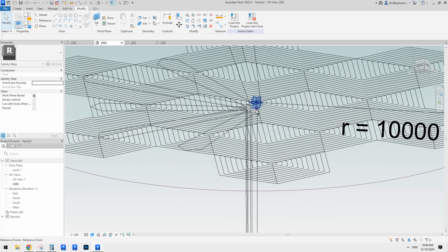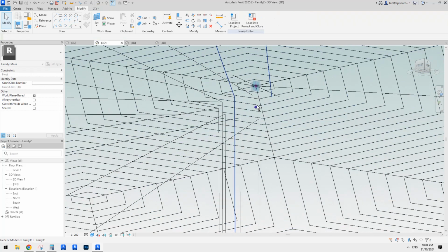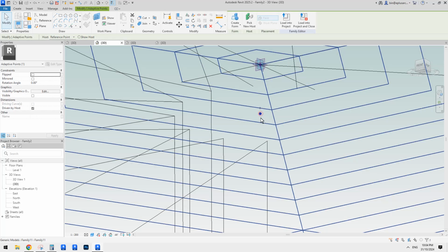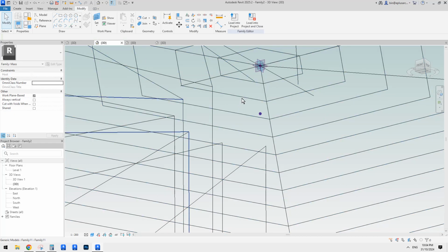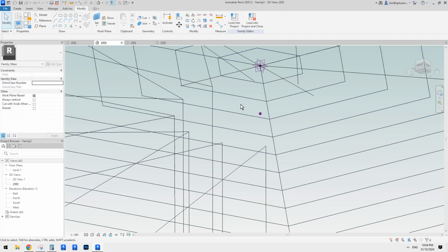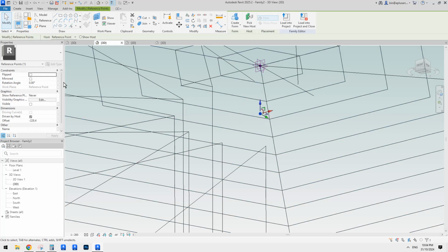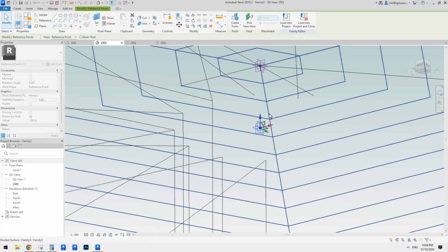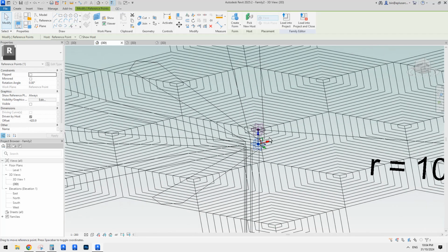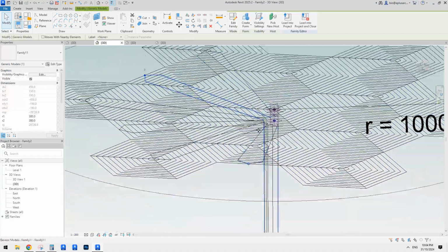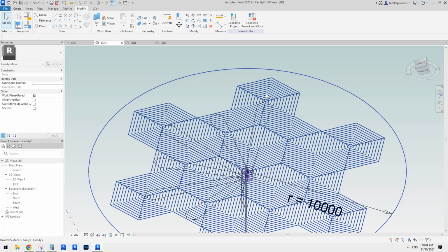Right. So if you want to, you can always... Oh hell! It looks like it's really hard to try to pick that point because there are so many adaptive points from the adaptive family. So let's see. Yeah. So maybe change this one to always. So this way we can easily pick this point. So you can see you can lower this down, and then all these adaptive families will adjust accordingly.